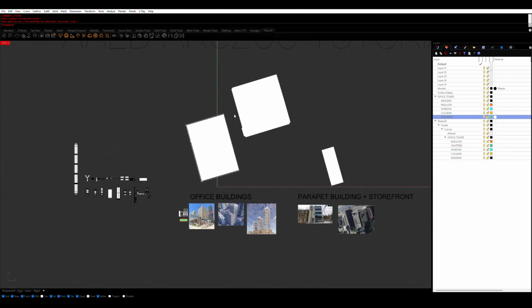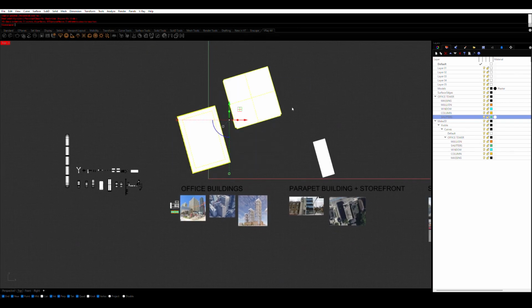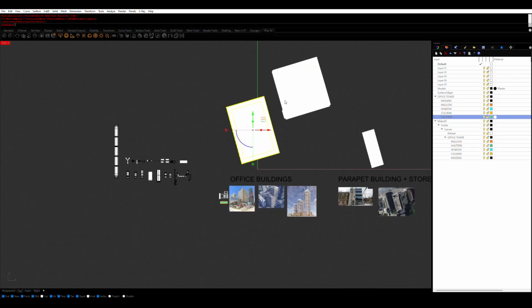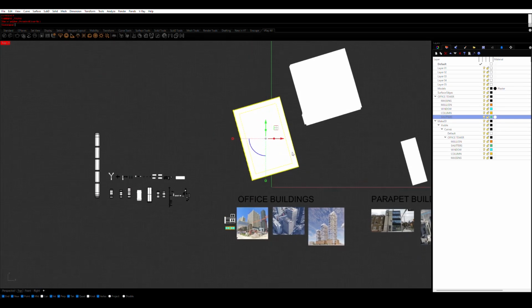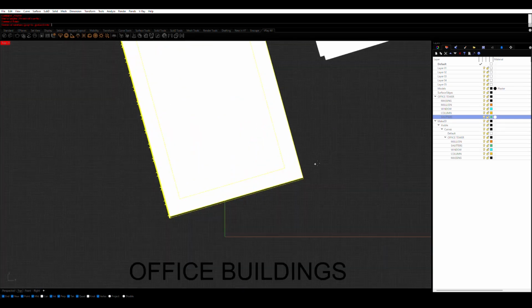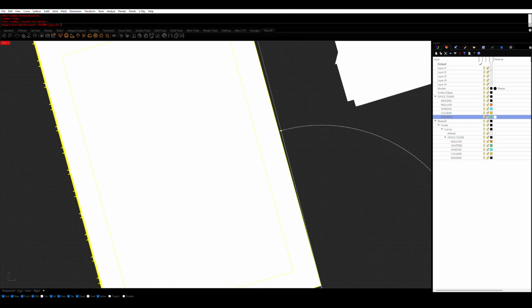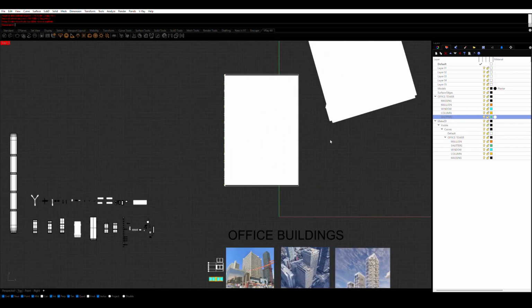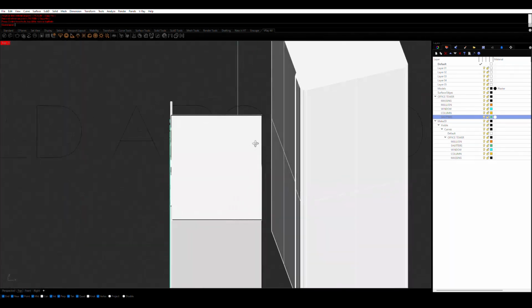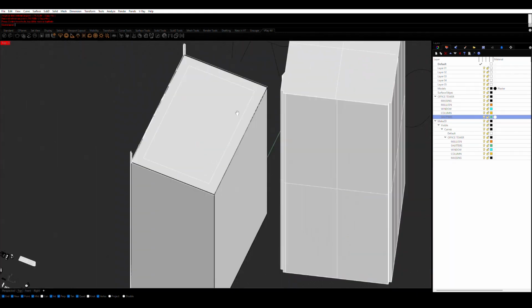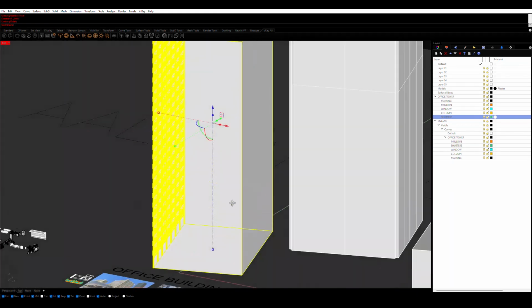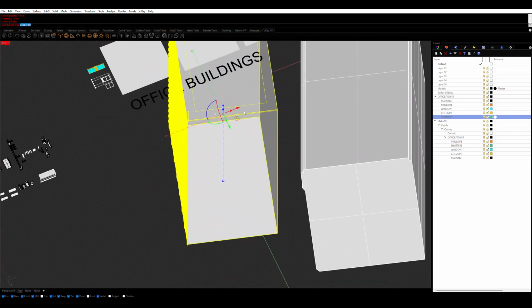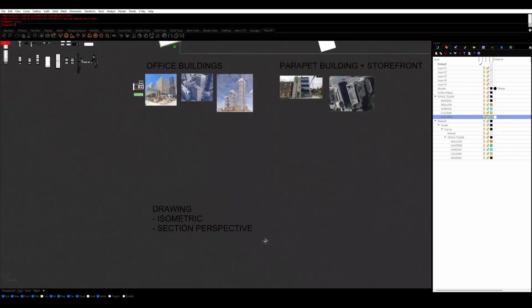And when working with buildings and modeling in general, it's always useful to have what you're modeling being on ortho. So I should have done this in the beginning, could have saved some time, but just rotate this. It's going to make things a lot easier. You can always rotate it back in place. What you can do is maybe save a footprint underneath.